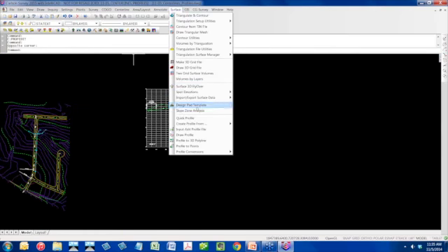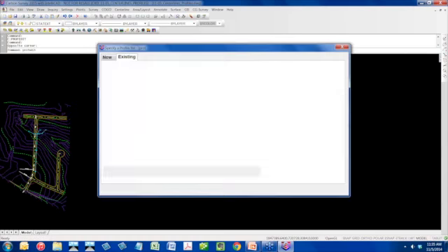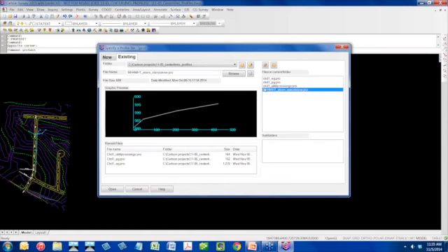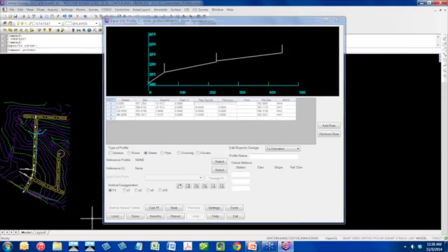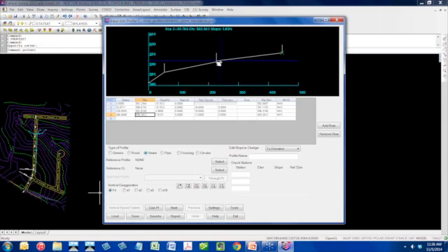If I go to surface and input edit profile file, you will notice that this is a profile file exported from Carlson hydrology. That is my manholes, from manhole 4 to manhole 1. And you can see this is a sewer type, so this was already created for me. If you needed to make your own, it's just that easy. You just fill in the blanks here and set the correct type of profile. You can see we've got a drop manhole here, and this will be an outlet at the bottom.